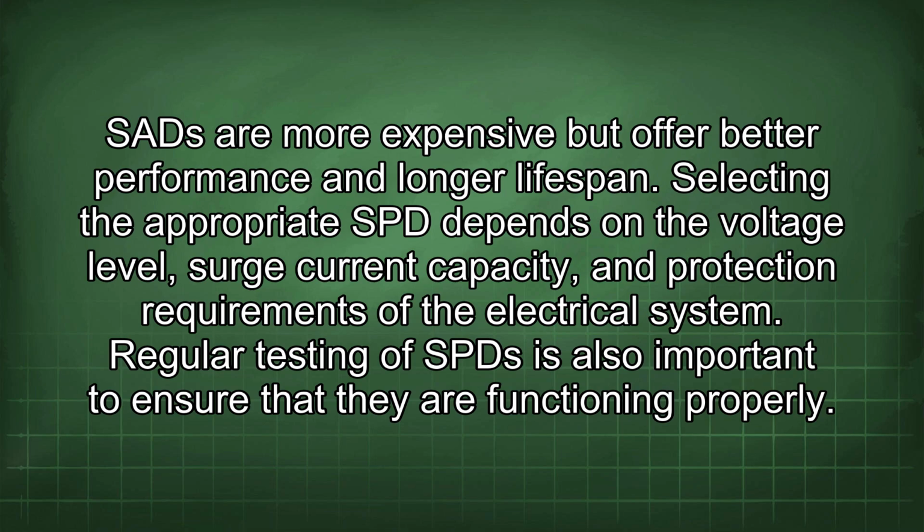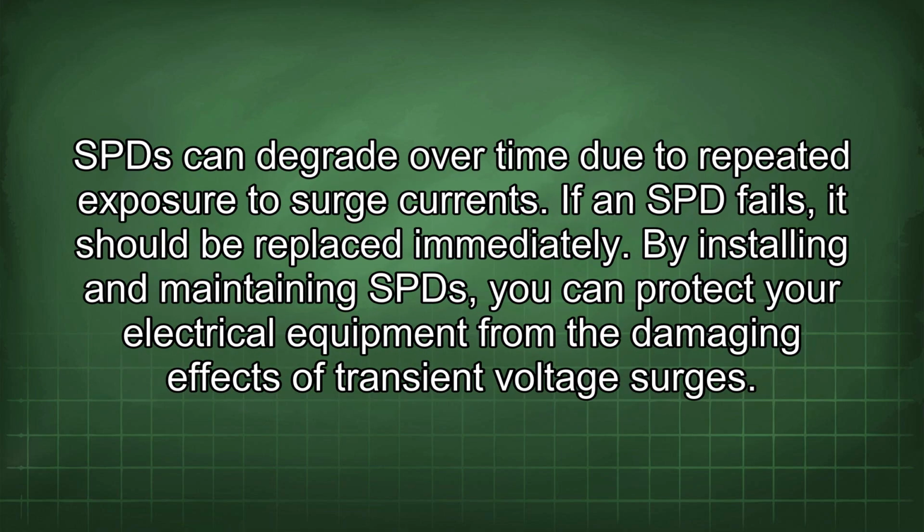Regular testing of SPDs is also important to ensure that they are functioning properly. SPDs can degrade over time due to repeated exposure to surge currents. If an SPD fails, it should be replaced immediately. By installing and maintaining SPDs, you can protect your electrical equipment from the damaging effects of transient voltage surges.